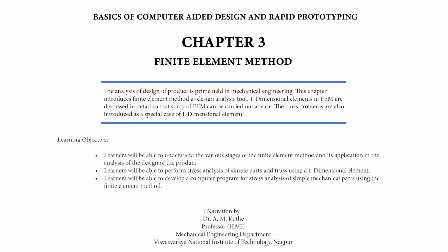Note, the boundary condition means knowing the value of the displacement of the nodal points before the solution. The strain and stresses of the element can be obtained using the formula epsilon equals BQ and sigma equals EBQ.